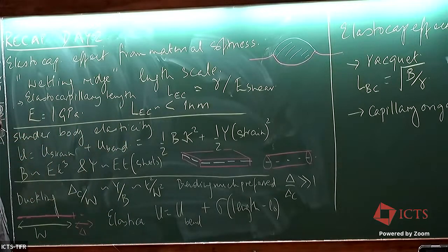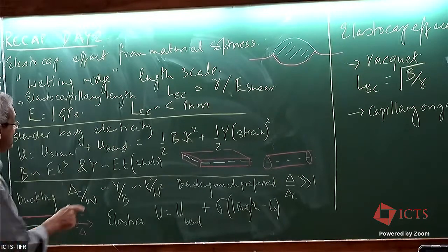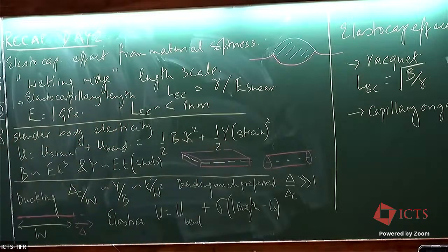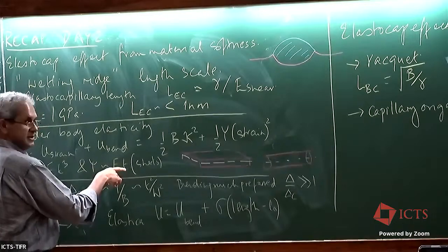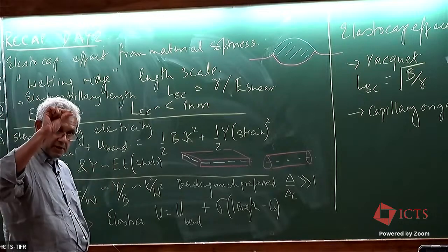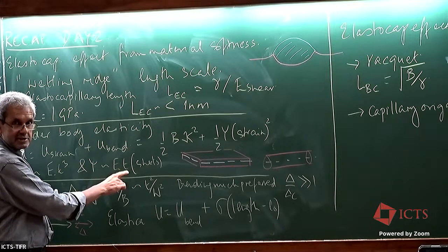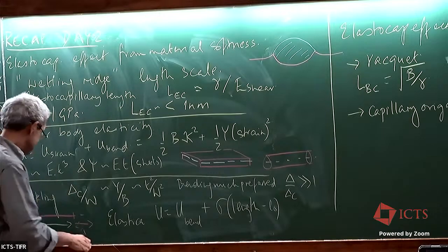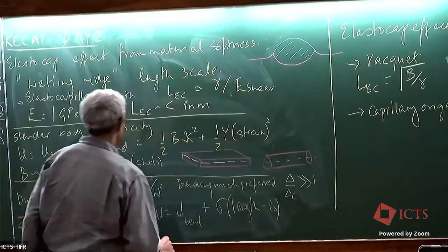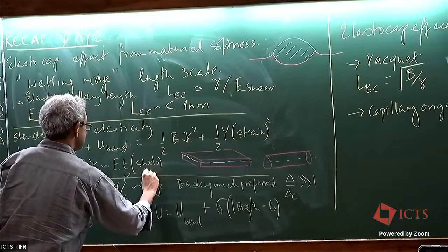We sat down and thought a little bit, did some hand waving and some dimensional analysis, and we decided how these numbers must scale. This is for sheets. The bending modulus should go with the cube of the thickness and the Young's modulus. The stretching modulus should go linearly, and then it should have a Young's modulus in it. So the scale for a bulk material reduced to a thin object is set by the same material parameter, but additionally, there's a very strong thickness dependence. Okay, we did a little tiny bit of hand waving to say for rods, this should be t to the 4th, t squared. Okay.